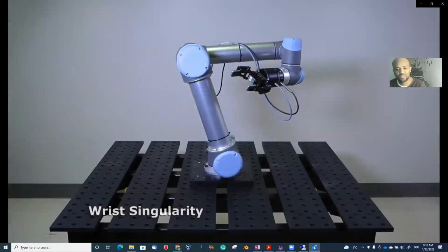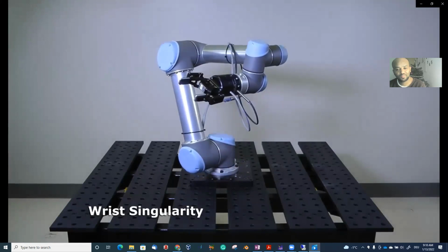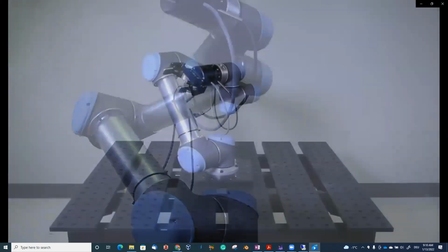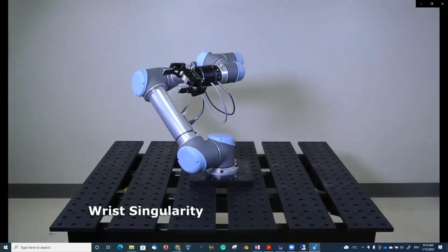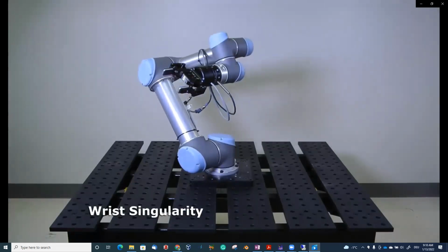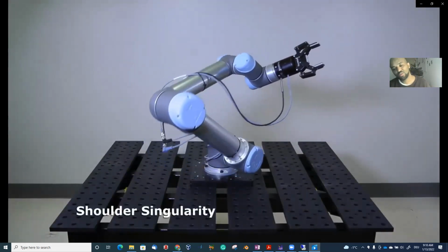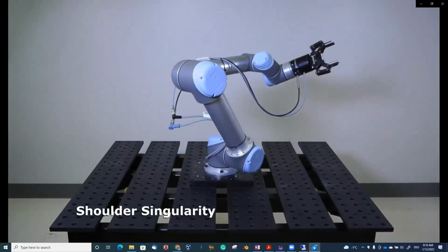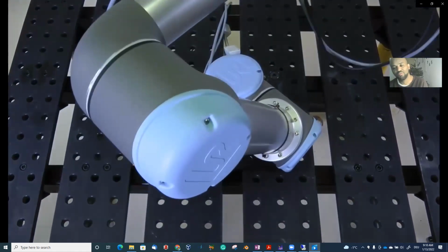In the video, at some places the robot wrist is making a rotation. This is singularity. This is singularity. This is singularity. Multiple solutions. Is the robot trying to pick some kind of object? Yeah, because the robot is confused about which axis to select. Look, now it is being confused. It's confusing the robot.